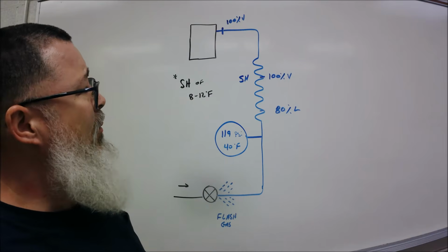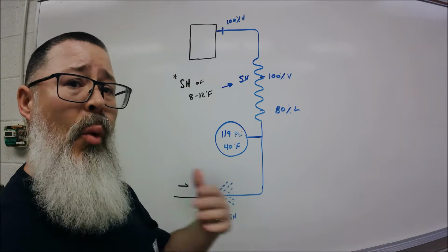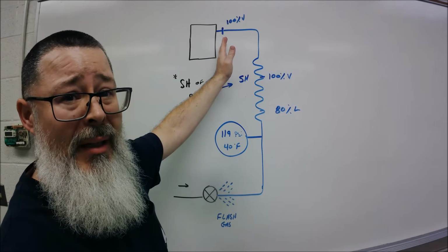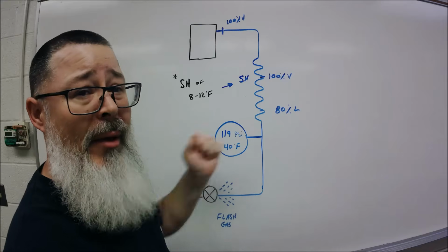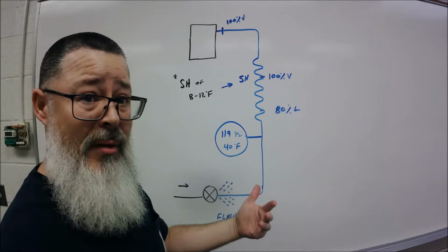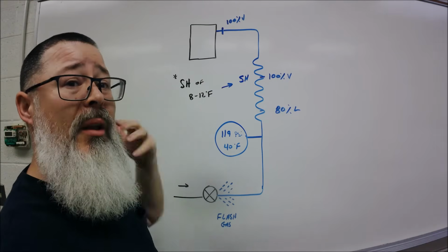but that 1 degree is not as much as 8 to 12 degrees, right? So we'll just say 8 to 12 is normally right there. But 1 degree of superheat means I got pretty close to that compressor with that liquid. Maybe I didn't have enough airflow, maybe I didn't have enough of a heat load on there, maybe I have too much refrigerant, but I got real close to going in my compressor with liquid.